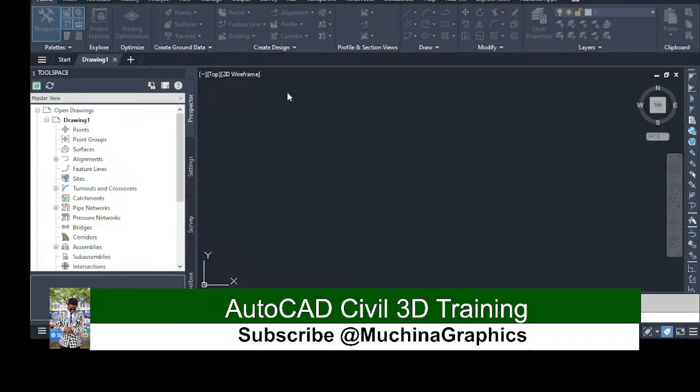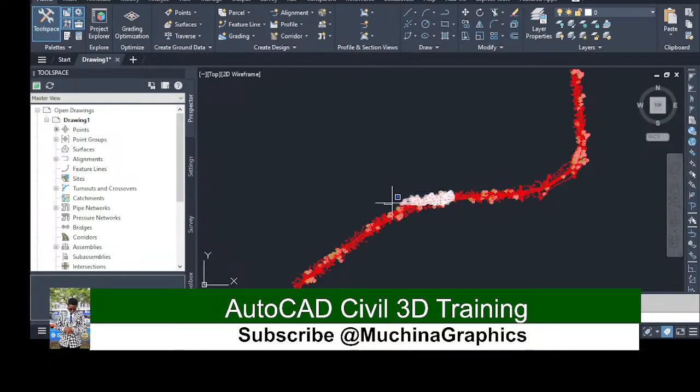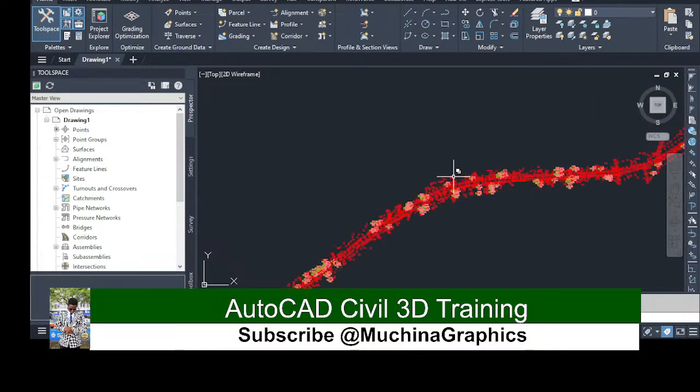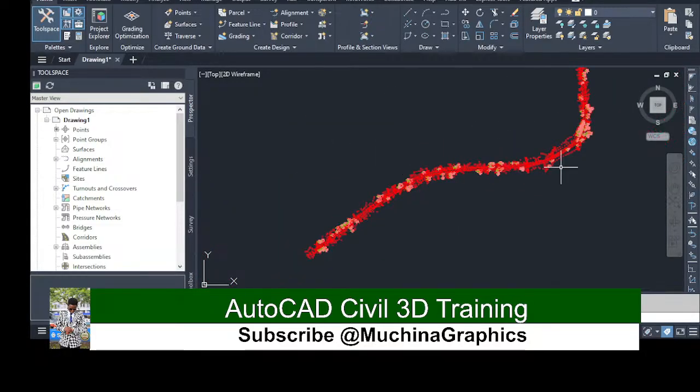After that, I will change the format to PENZ format, that is the point number, northing, easting, point elevation, and description. After that, I will click OK. After that, you will not be able to see your points, but what you need to do now is click the zoom tool. After you click the zoom tool, you click in your workspace and you will see your data like that. So I'll give you a minute to try and do that, and then we'll try again with you.